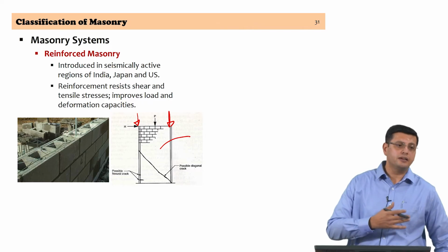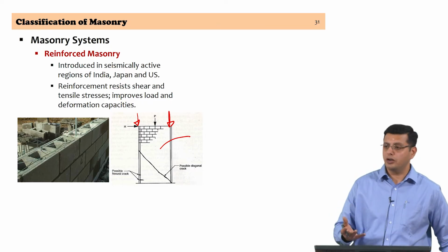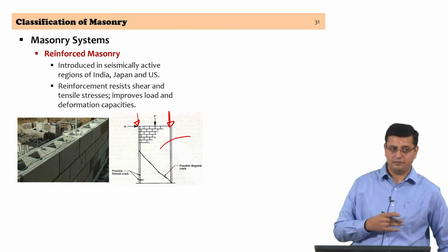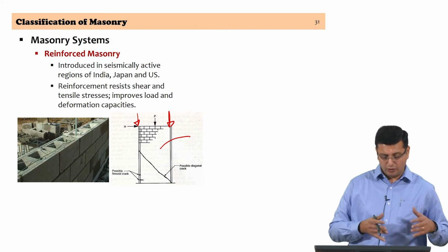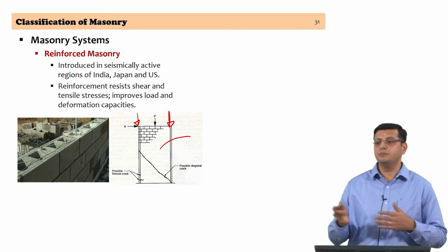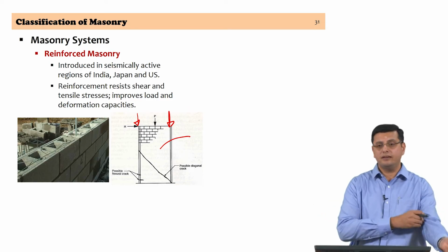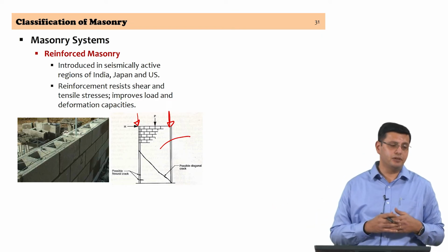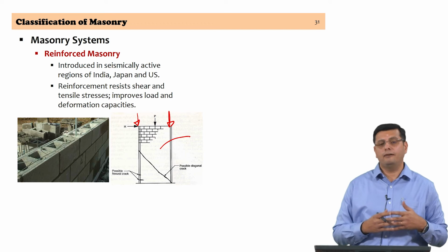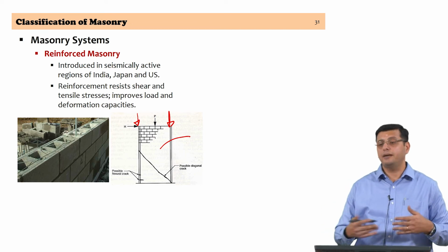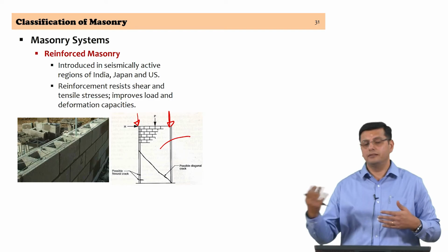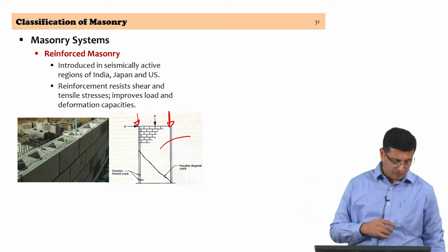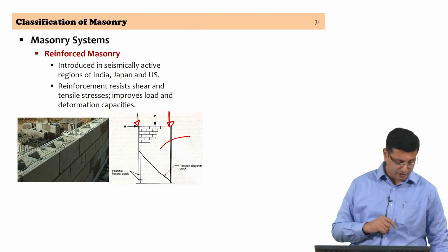So, considering concepts that come from reinforced concrete, distributing the steel is a good practice. So, you should be able to look at configurations where steel is being distributed across the masonry walls, so that distribution of cracking is achievable, and if you distribute cracks you get better deformation capacity, because your steel can then possibly start yielding as the crack propagation progresses.